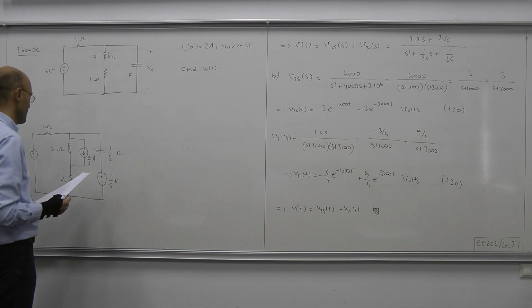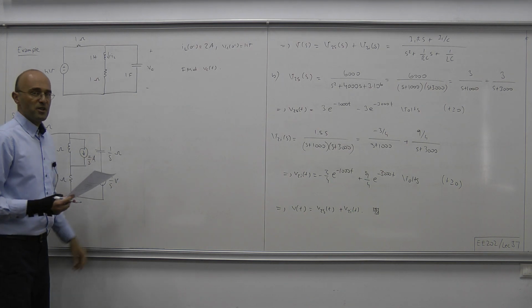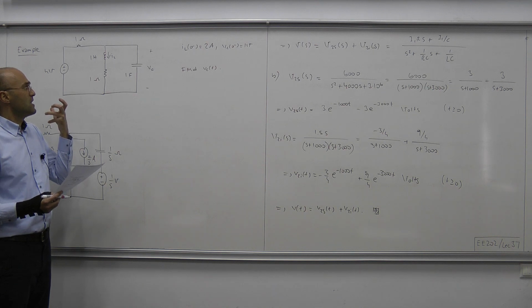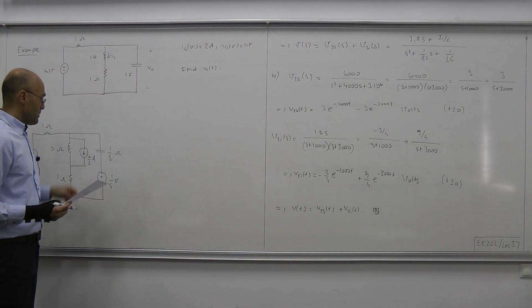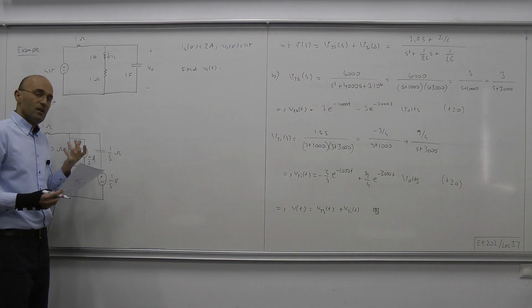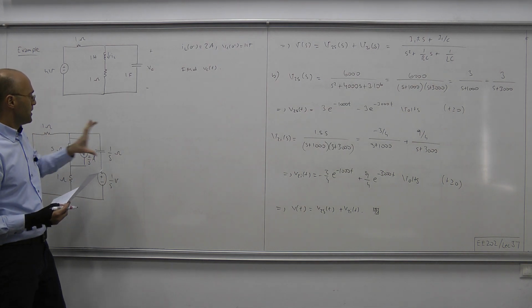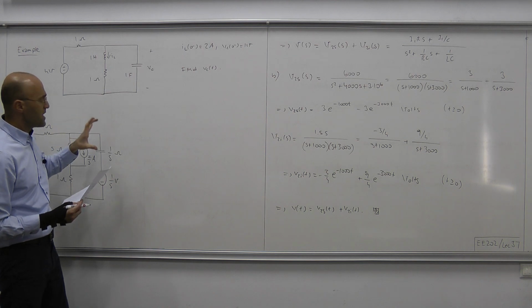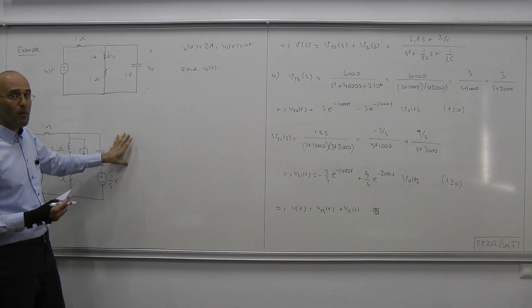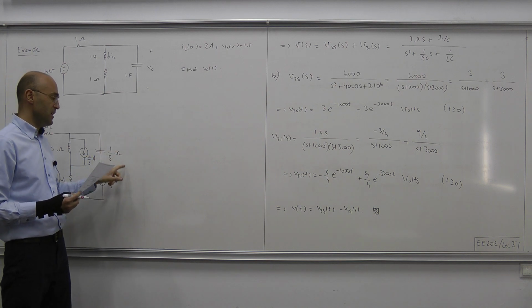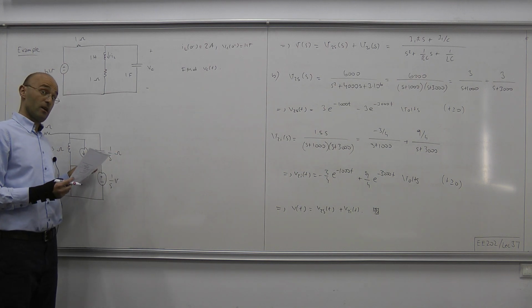Now, in this representation, what's the capacitor voltage and what's the inductor current? It's a common mistake to mark the capacitor voltage in the S-domain circuit as simply the voltage drop across the terminals of this impedance, because this looks like a capacitor.